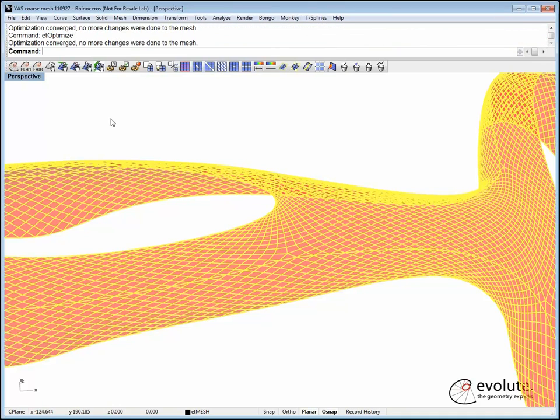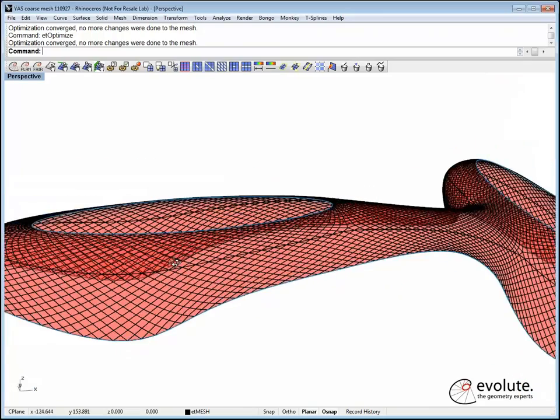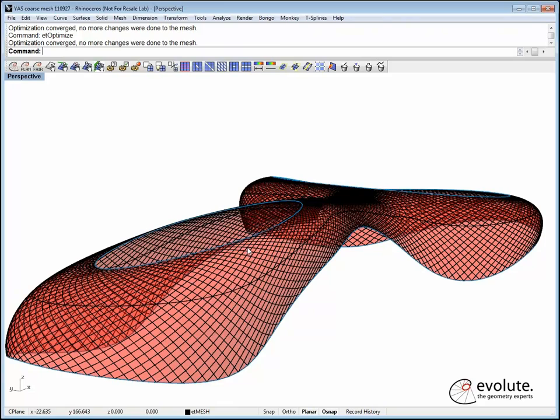Yeah, this is basically the optimal solution for this mesh currently. But we tested the ideal edge length optimization, and it works quite nicely. But as I said, it is highly dependent on the filling of panels onto your reference surface, because it depends on the aspect ratio of the panels from the coarse mesh and how they are distributed over the reference surface.